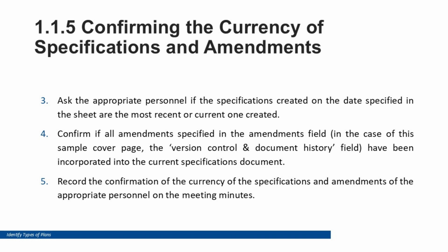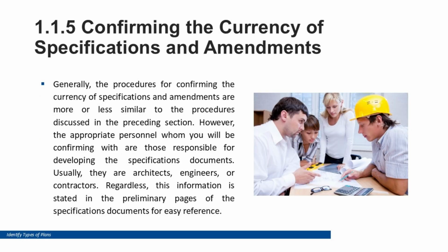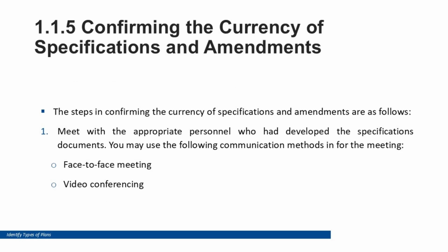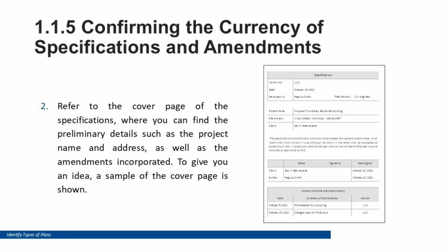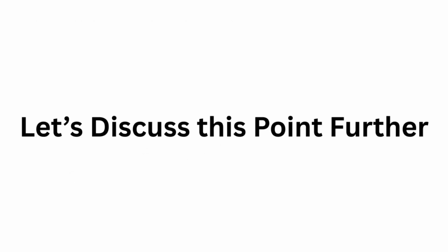Once you identify the most recent revision entry, confirm with the appropriate professional, such as the architect, structural engineer, or services engineer, that the plan incorporates all approved updates. Only after this confirmation should you begin using the plan for construction, costing, purchasing, or supervision tasks.